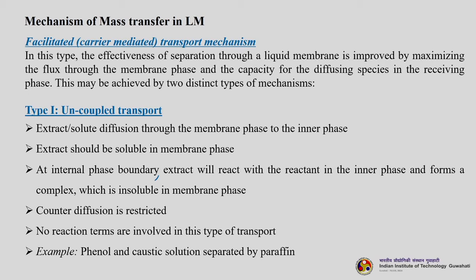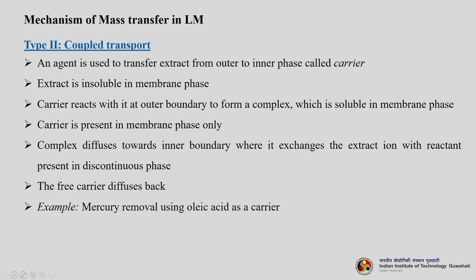Now, counter diffusion is restricted. No reaction terms are involved in this type of transport. One classic example is phenol and caustic solution separation using paraffin. So, this is uncoupled transport. So, nothing is getting coupled together. And the second is coupled transport.